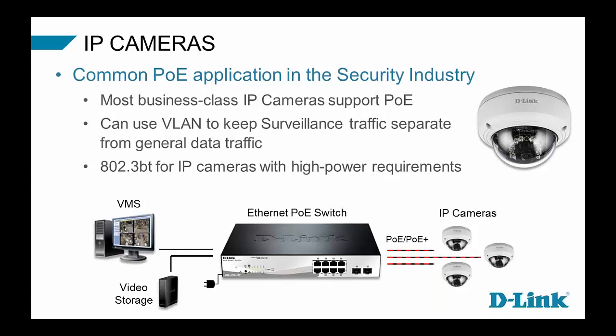And as I mentioned here, the new standard 802.3bt is really becoming more prevalent, really ideal for IP cameras that have high power requirements. Need an IP camera that's going outdoors that needs more than the 30 watts that were previously available by the older AT standard?